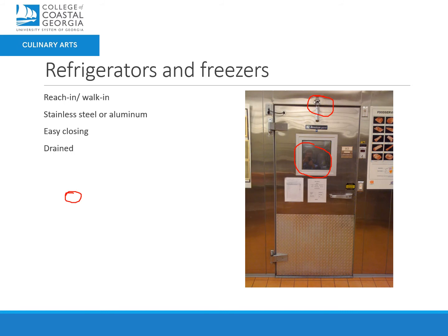But just as a management thing, if you ever go in a walk-in and it smells terrible, like it smells like sewage, something you may want to do is to get a glass of water and pour it in the floor drain. Because what happens is the floor drain goes down and there's an elbow under the ground. And that elbow, it's just like the one under your sink, and it's full of water. So this is all water in here.